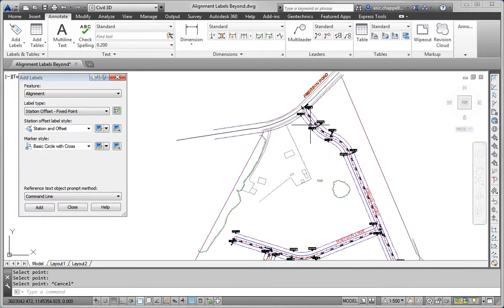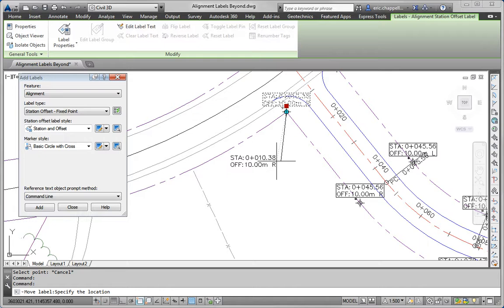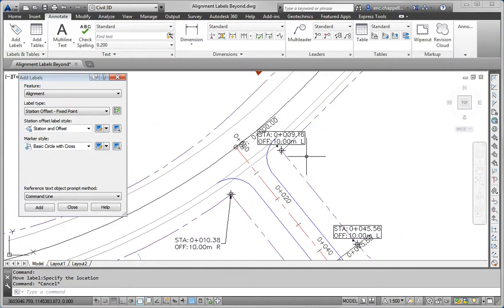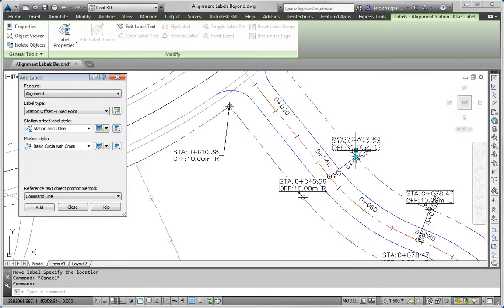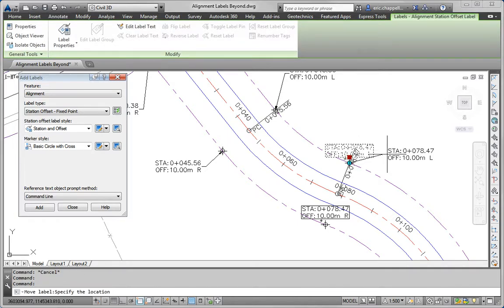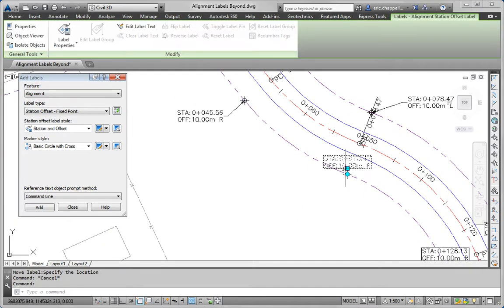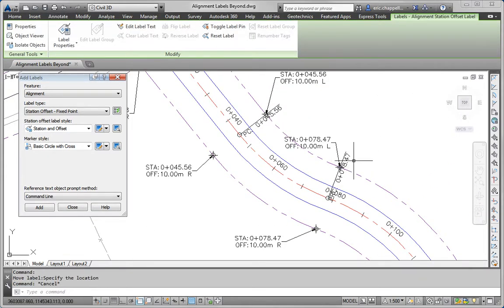So now what I want to do is make this look a little cleaner, so I'll click the labels and drag them out to some open space. That takes away the box around the label and makes a leader appear. So I can move these labels around to locations that are better suited.